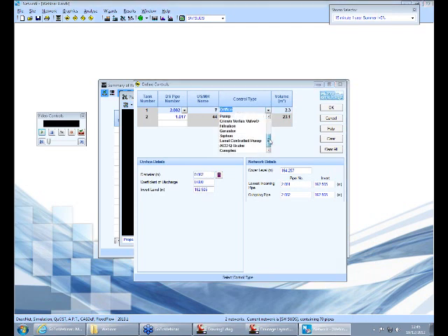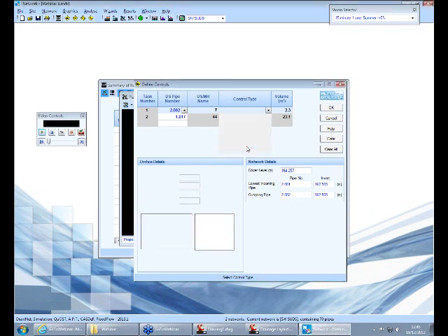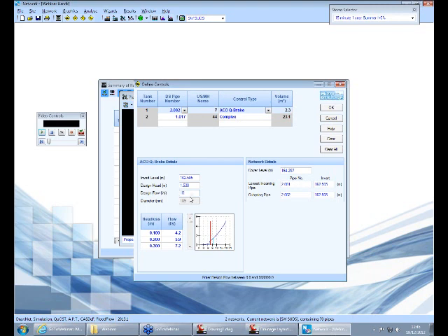So instead we could switch it for the new ACO Q-Brake, a new flow control which has gone in in 2013. To specify the Q-Brake, it's very similar to the orifice. You just need a design head and the design flow. Once you have both of those in, it automatically calculates your head loss and flow, so your depth-flow relationship. And you can see by using a vortex control instead of a standard orifice, we get a diameter of 109 millimeters, and so it should be adoptable now at that location.